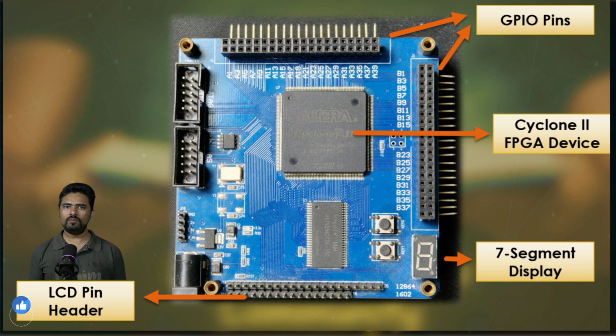Next, we will dive into designing a shift register on the FPGA development board. This topic adds a bit more complexity to our project. We will develop a 4-digit 7-segment display on the board to show a number that corresponds to how many times the switch has been pressed. This project adds a practical aspect by interacting with the board and its components, and it will add a hands-on element to our learning experience.